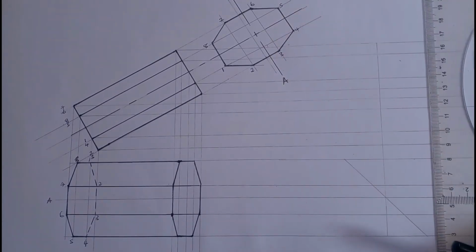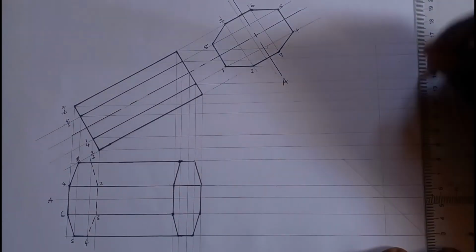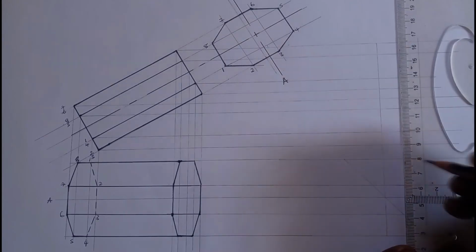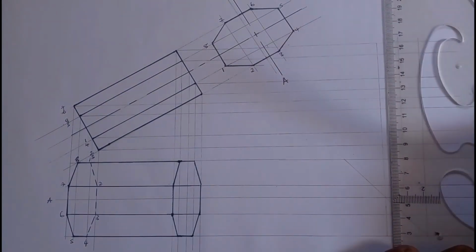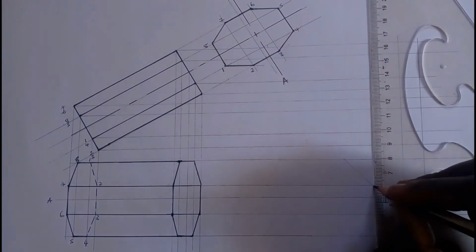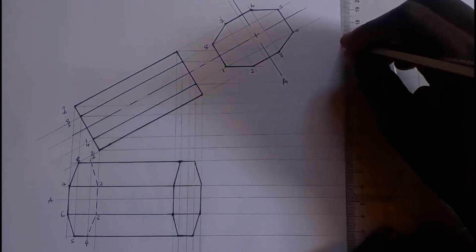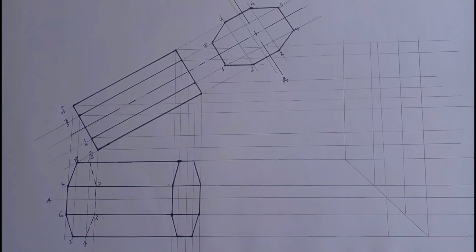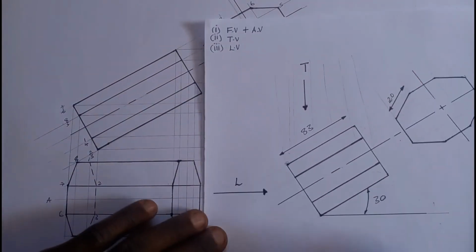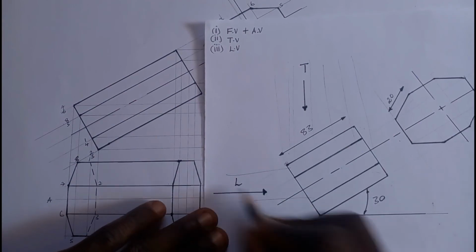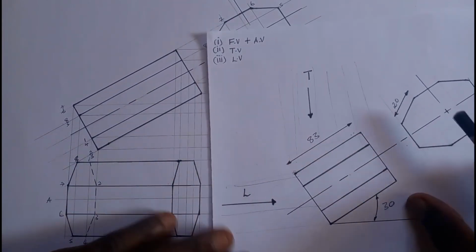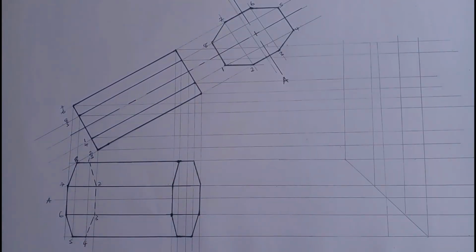And now I'm going to project these lines upwards, this one. I'm going to project this one again. This one is already there. This one and this one. Just like this. So when you look in the left view, you're going to see this base. If you project some line there, you can see the base, and right here you're just going to see the corner. So that's what we're going to do.